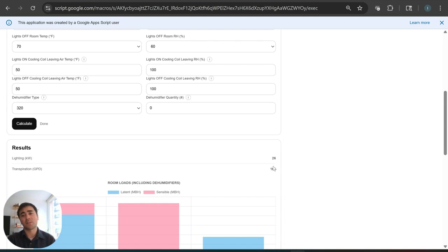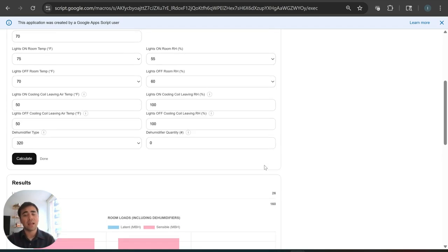It's nearing closer to a ton per kilowatt, which is quite a bit of capacity, and maybe too much capacity, depending on how much the equipment is able to turn down to match the load when the latent load is smaller during early flower and when the temperature and humidity set points are higher.